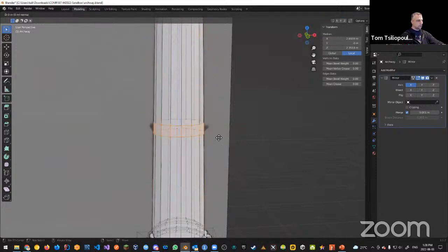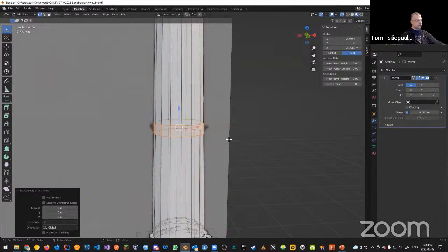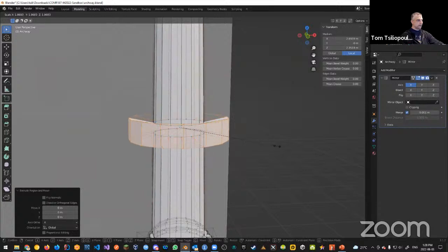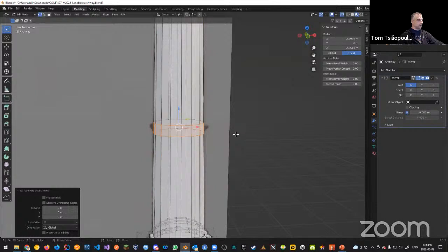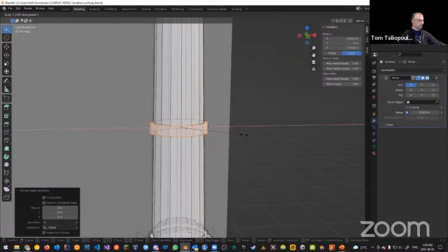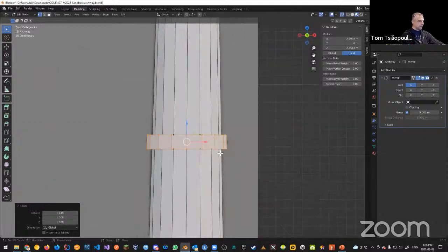I could extrude and then I could move it out, but that seems also weird. However, if I extrude and then scale, I get that thing that I want, but it scales it kind of weird and fat. So I want to scale only across the x-axis first. So scale this way. That's pretty good. And it looks like my scale is 1.15 across the x-axis. And I can duplicate that scaling across the y-axis, 1.15, so that I can have a symmetrical scale.